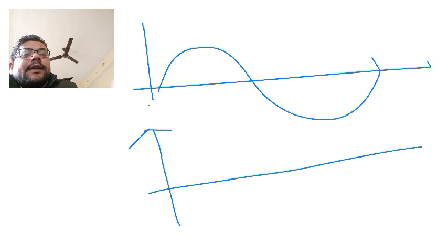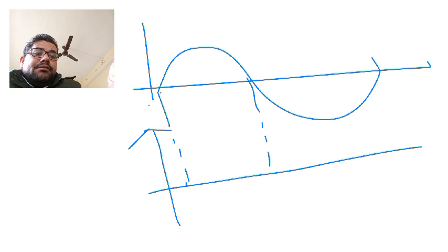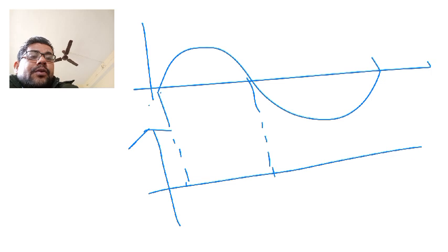During the positive half cycle the output was 0, because the diode was a short circuit. During the negative cycle the output was 2 Vi.